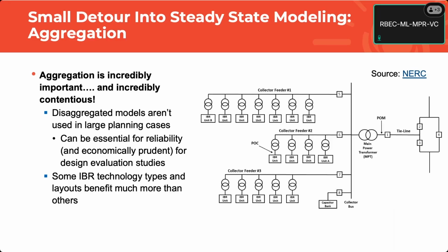When you're trying to study these things as a whole, the other consideration is that a lot of these technologies are voltage dependent. If your voltage is right at unity, 1 per unit, you have a pretty good reactive power curve, right? There are technologies where even if the voltage strays a little bit, 5% either way, you still get the full capability, right?